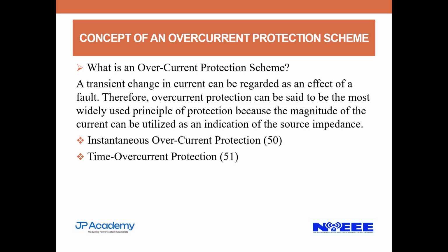Then if we come over to the distance protection scheme, distance protection is a non-unit system of protection. So basically, the distance protection scheme measures impedance. It measures the impedance between the location of the relay and the point where the fault is incident, then compares it with its set values. Once there are discrepancies, it trips. Distance relays are usually employed on very long transmission lines.